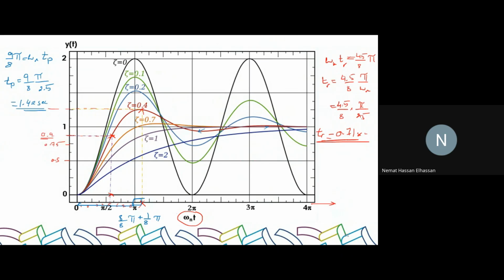Just by looking, aren't all the signals, the waves, underdamped? Is the black one underdamped? If you look at the two peak values, both are hitting the same peak value of 2 volts, right? If you look at the purple one, which is equal to 1, you'll see that it reached the steady state faster than any other curve, right? If you look at the blue one, you'll notice that it's not fluctuating positive or negative, but it's gradually making its way to become stable. Make sense?